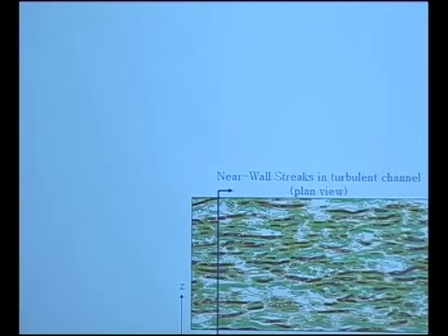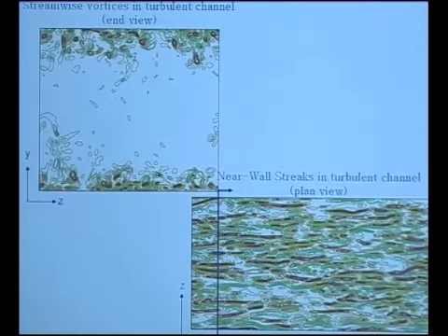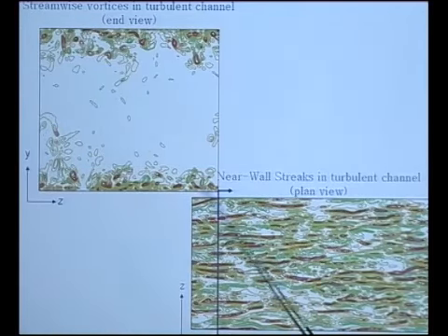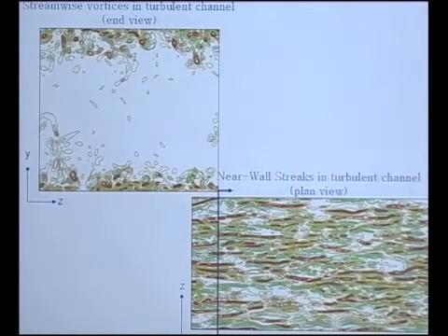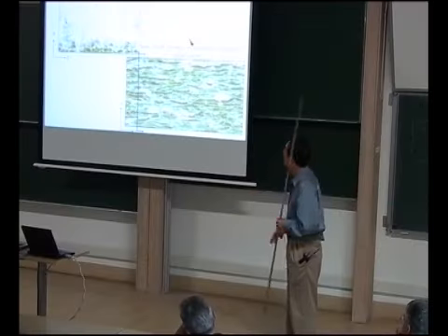It's just the small regions of very high skin friction, and when you add it up, that's the turbulent skin friction average, which is high. Now, if you cut across this, every region that has a high skin friction is highly correlated with the streamwise vortices.